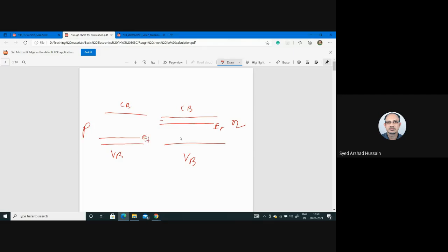So now when you form the barrier, I mean the PN junction, you should know that you are not forming a PN junction just by touching these two pieces of semiconductor. It's not like that. You have a common piece of semiconductor and you do doping, considering a plane, and on either side, one side with P type material or trivalent impurity, the other with pentavalent impurity. Then only your junction or diode is formed. So this is the p-type semiconductor, this is the n-type semiconductor.